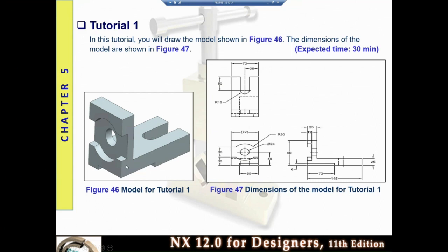There are different ways of doing it. Technically, you are creating that block, doing that cut there, or subtract, let's say. Then you have an extrude from this one, and a cut, and another cut. This is one way of doing it. There's another way: you just create an L shape and extrude. Once you extrude it, do this cut, do that cut, create that cut, and create the other cut.